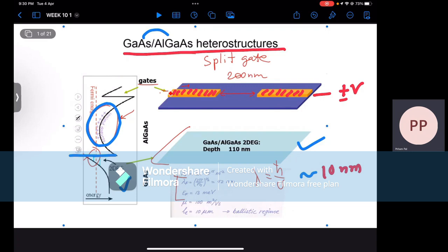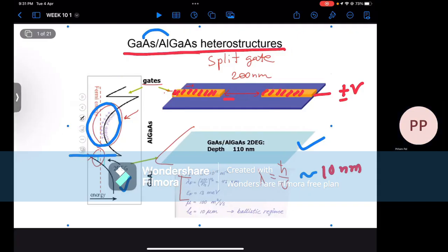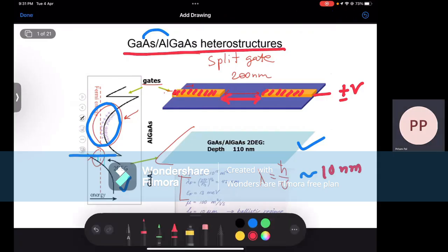So it's the gate, as I mentioned. It's placed on top of the crystal. The two-dimensional electron gas is 100 nanometers below, and these are metallic structures which can be nanofabricated to also be of nanoscale dimension. For example, this gap that you can see here is in the nanoscale and can be tuned down to 200 nanometers. Such a tiny length scale, right?